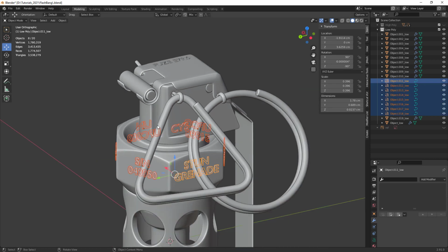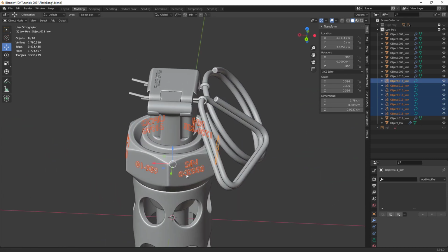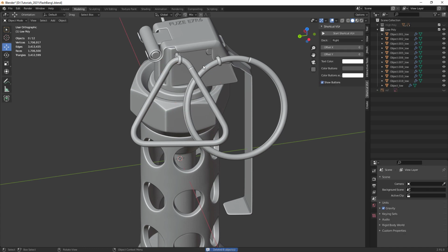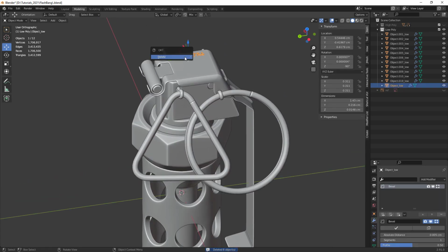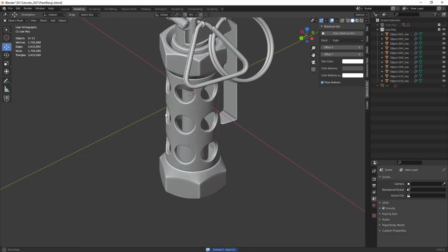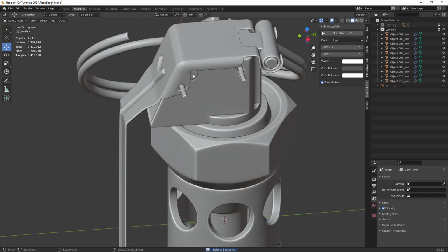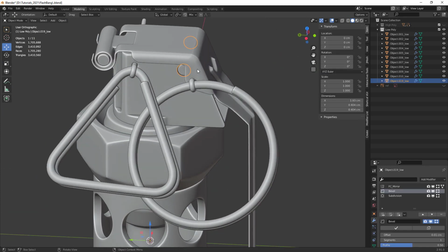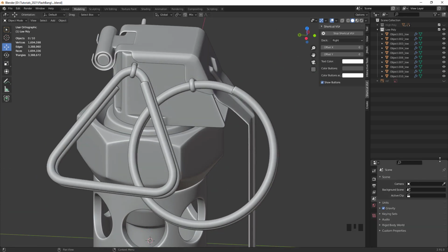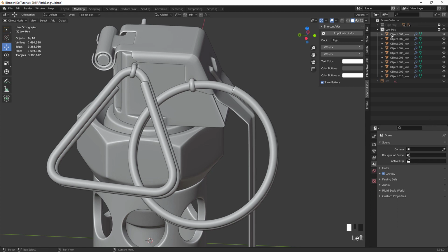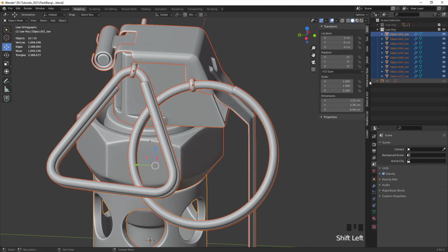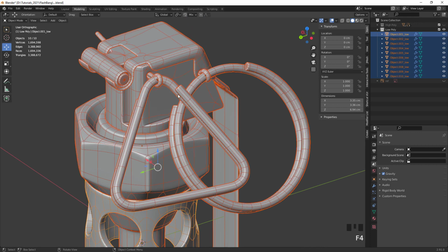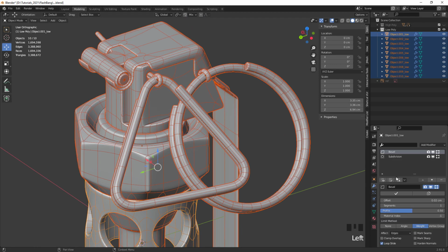Now here on the low poly, what I want to do is select the text, which we see in our scene collection, and just delete it. And then manually also let's delete these floating elements for baking. Let's get rid of it. And then here on all these objects that we have here, we can now make use of this awesome plugin that we downloaded earlier.